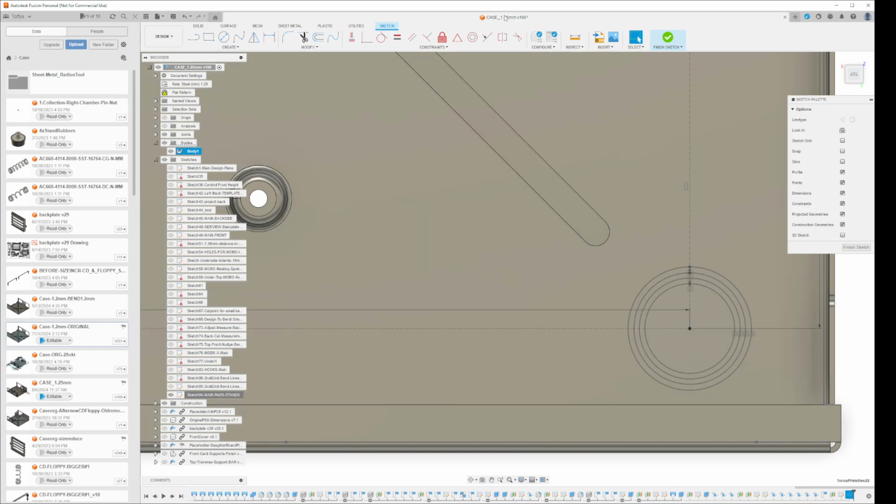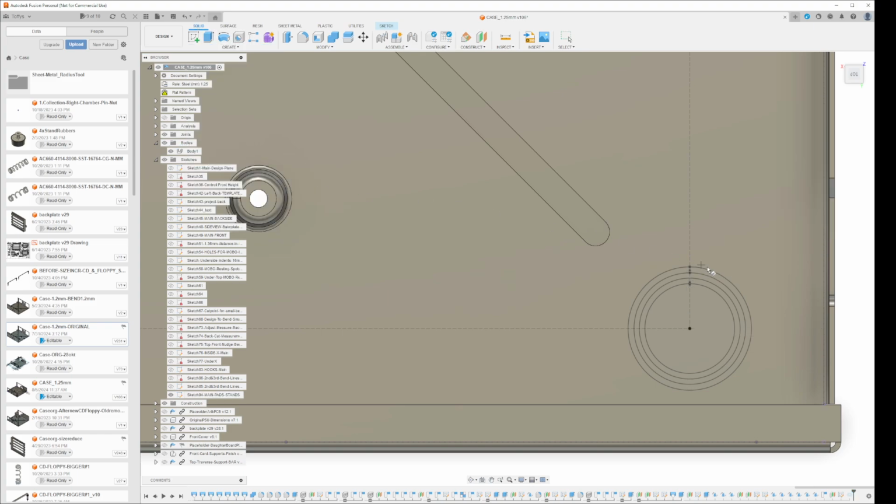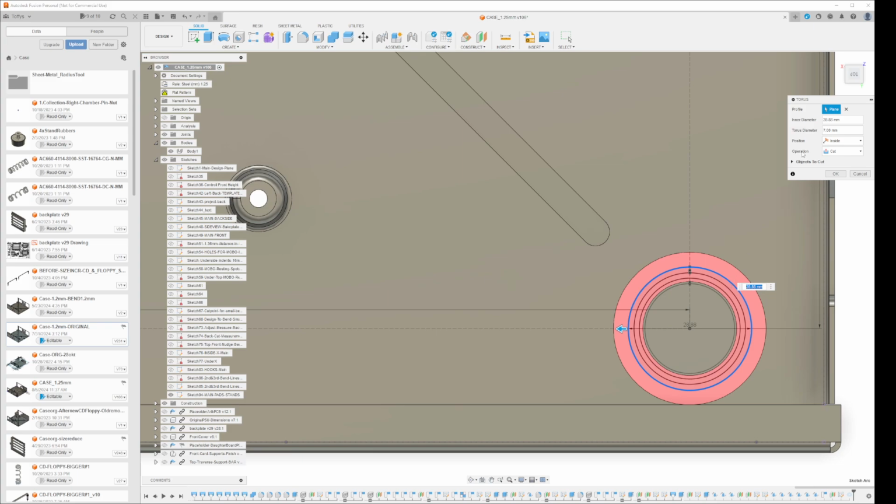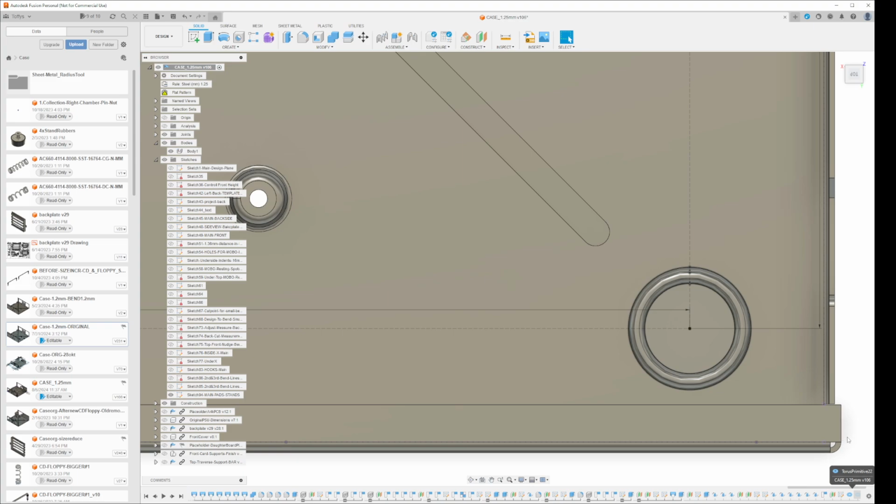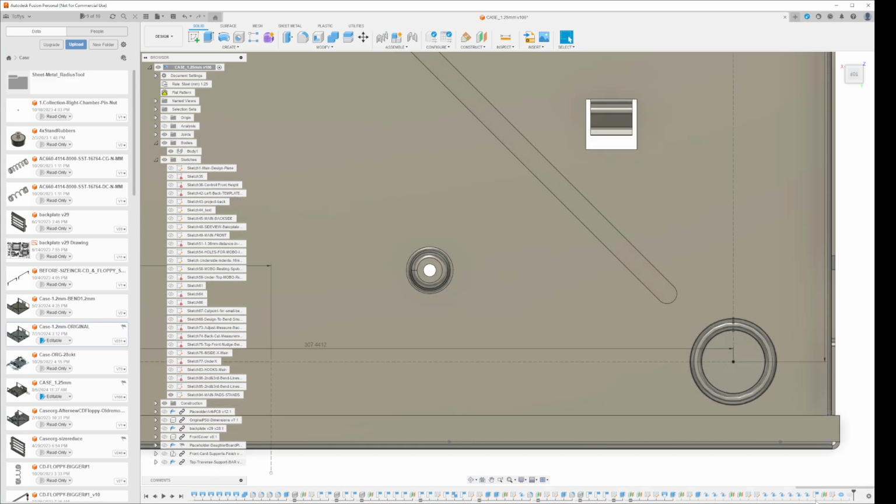Now I'm in sketch mode, I go to solid, create, and a new torus. Same operation here. Then I set the size as I want, and join. What happens now is that it creates a new model, but it refuses to unsuppress the previously made one. Now when you go down and see here, the marker is here, but there is no way to unsuppress this. I can select roll history marker here, but that will make it bug out.